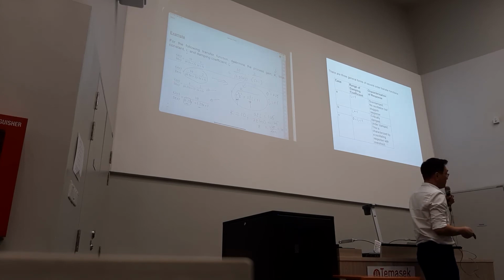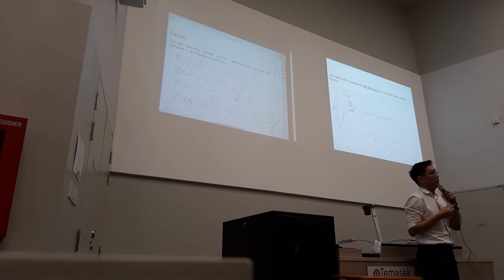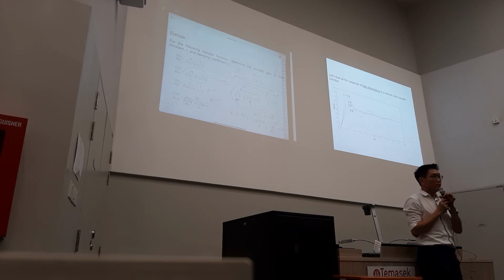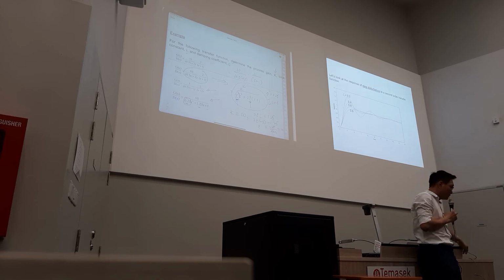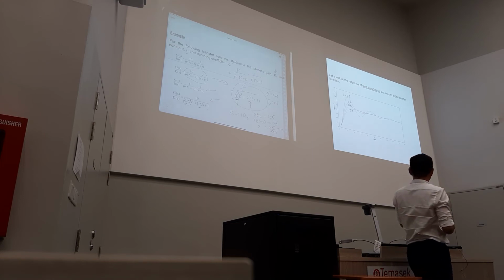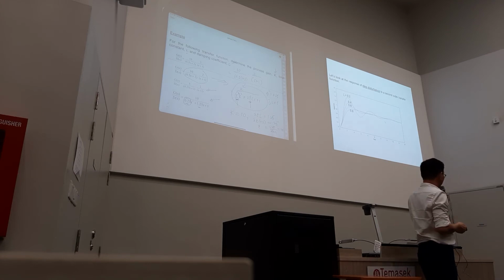And what does it mean? This is how we look at the disturbance or the response itself. But this only happens for a step disturbance. Step disturbance means the change is only d over s, for the second order transfer function. If the damping coefficient is less than 1 but more than 0, we will have these types of oscillating response.